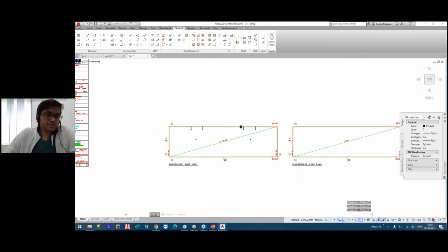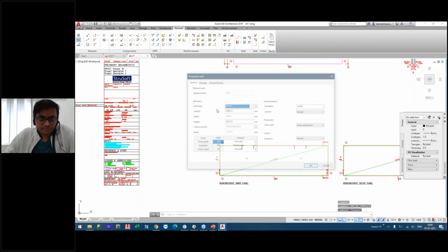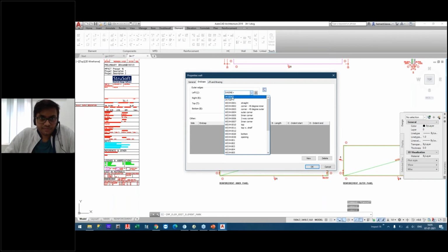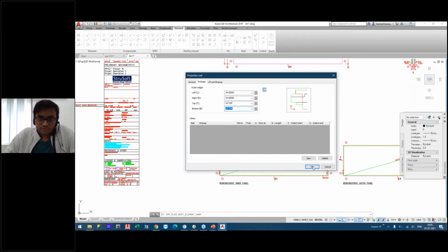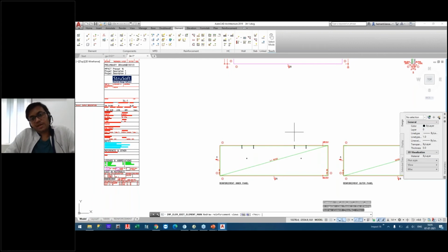But as we saw earlier, we also defined our end cap reinforcement sizes. Now this particular wall doesn't have any end caps, so if we add end caps, we'll just configure our end caps from here. I have some of the end caps made before, and I'll just click OK. So again our panel will be redrawn. I will just click yes to everything, updating the lifts and bracings.